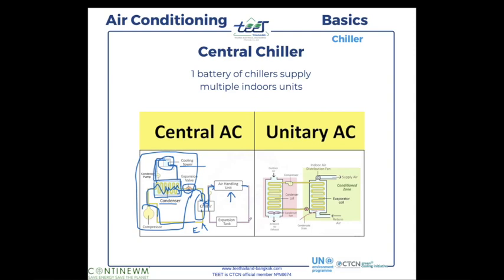And here we absorb the heat from the room and bring the heat inside the coil, inside the water. There is a tank in the middle because we use water. So the water at the intake of the AHU or FEU or whatever is cold, and at the outlet it is hotter, okay? If you take the difference in temperature, it is hotter because you absorb the heat from the air in the AHU. Then it goes back to the chiller to be cooled by the refrigerant fluid, okay? So if you compare these two images, you realize that you have exactly the same physics principle, whether in a chiller or in a direct expansion unit.